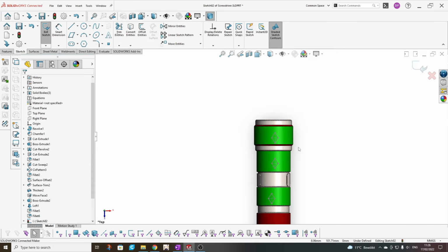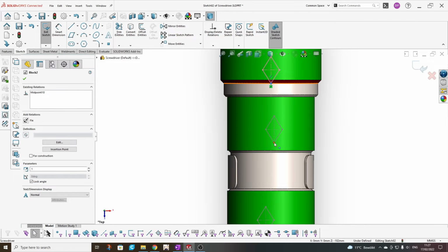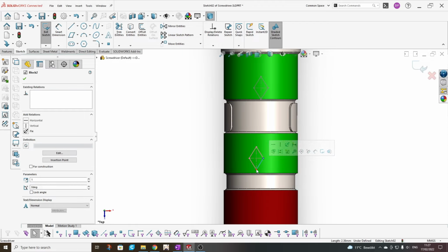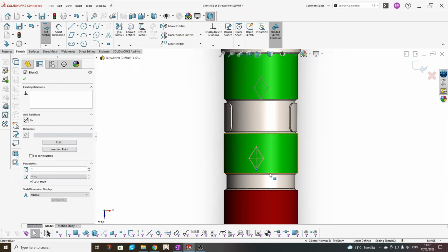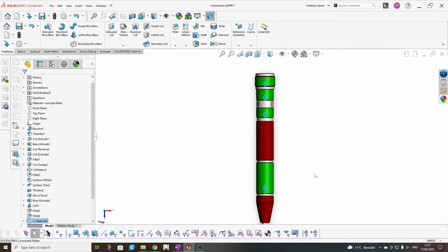I didn't define the insert point of the block, but it's not so bad when you're working with a lower count of instances. Don't forget to lock your angle when positioning your guiding blocks because it can move. So I have the guidance on all 4 places.